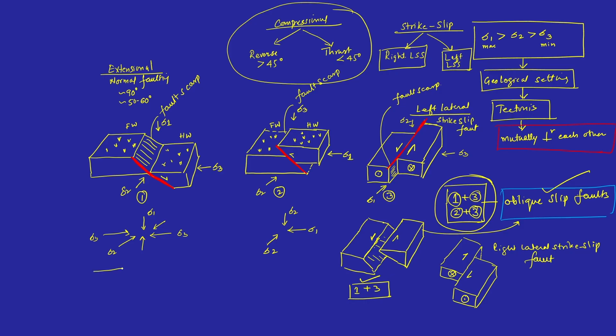If you have normal faulting like this, initially the movement is along this fault, where this block has moved down, and after the erosion of the scarp, we will see something like this, or maybe further like this, where you have the colluvial wedges and all that. So you have the scarp finally left out, something like this.